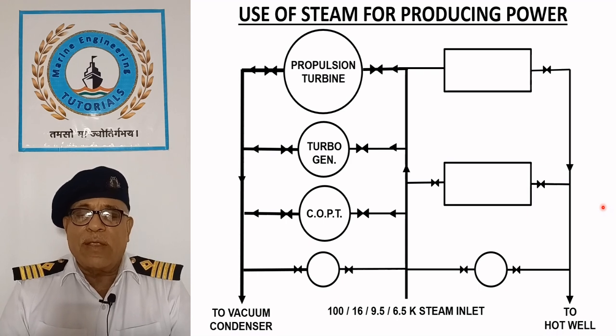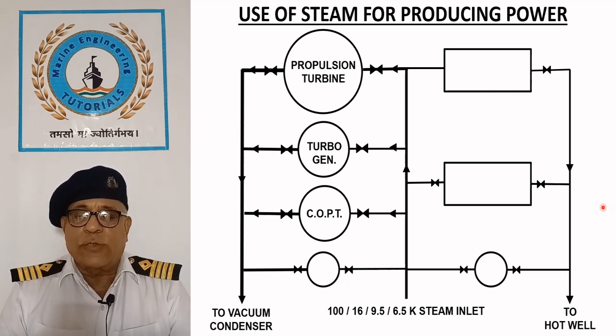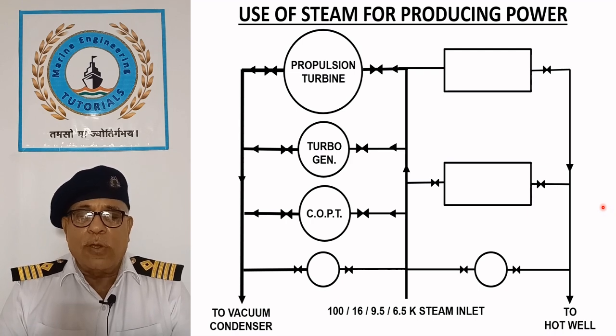On conventional oil tankers, steam turbine driven cargo oil pumps are used for the bulk discharge of cargo oil. These pumps typically operate using 16 bar saturated steam, throttled down to below 9.5 bar.